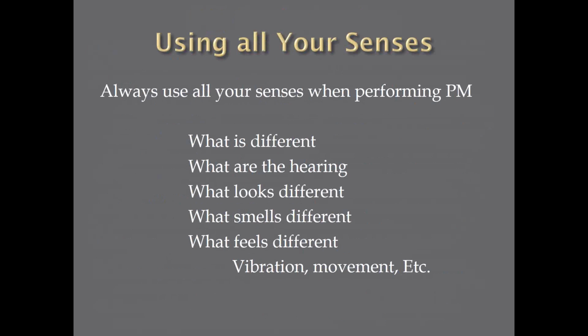Using all your senses, what are your people looking for? When they go to do a PM, what is different? Using the sense of hearing, does it sound different? Does anything look different? Is there movement? Does it smell different? Sometimes when things get hot or oil starts getting oxidized, it'll smell different. What feels different? Using that sense of touch, vibration, is there movement?